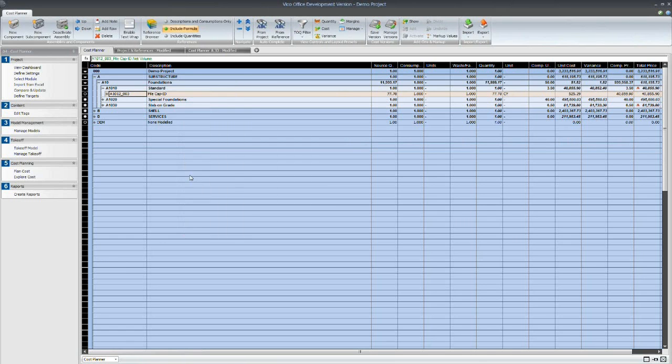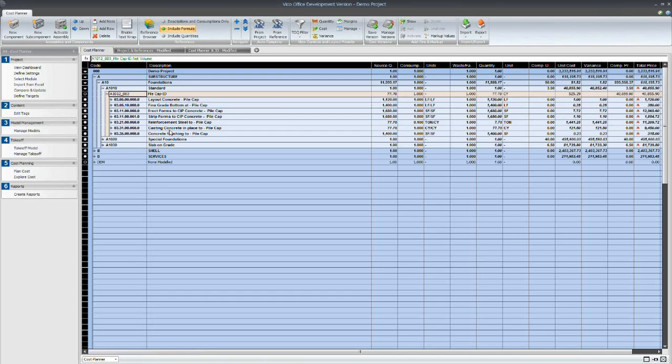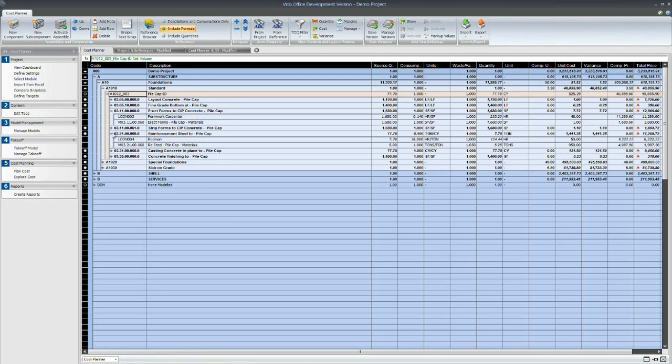And then if I just use the pile cap as an example, I could have a pile cap and I'm just going to deactivate assembly. So what this means is I've got a quantity there. I'm using the net volume of the pile cap, and I've just put an allowance in of 525.29 per cube. Okay, then so that's maybe an early phase, and you've got pile caps, maybe just schematic. And as the design develops, and I now find out its particular grade of concrete and its particular size of steel, I can add another level of data, more granularity, and then we've got these broken down into their pieces as well.